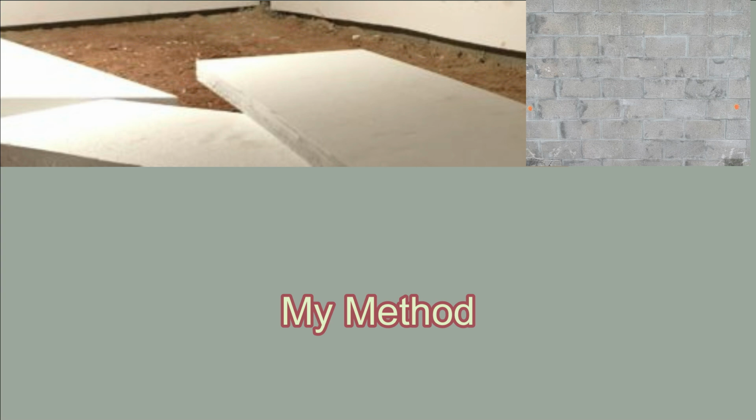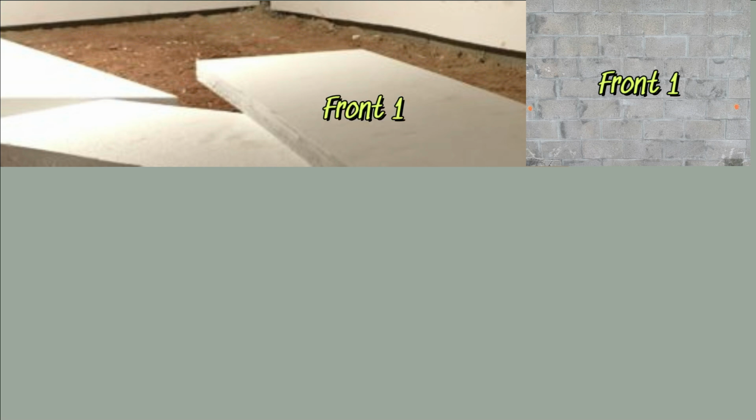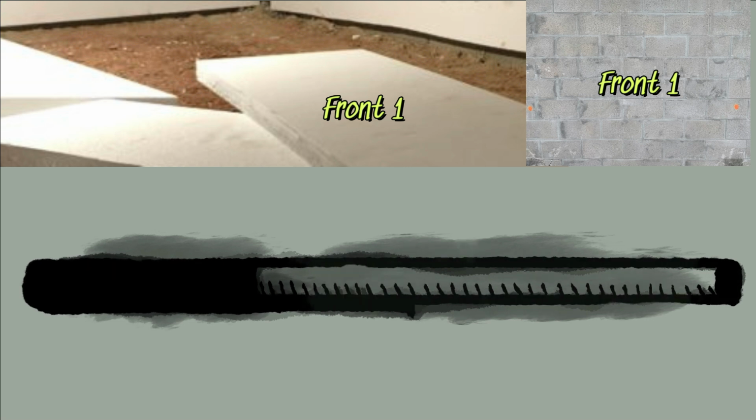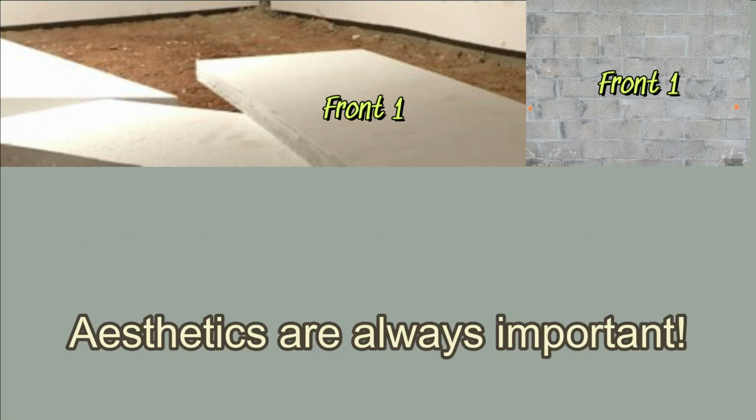I use a method of writing on the block walls a number, and then writing a number on the corresponding foam board piece in magic marker. I always write the number on the side of the foam board that will not be visible when installed. This is because you may not always be encapsulating over your foam board insulation and don't want the writing to show for aesthetic purposes.